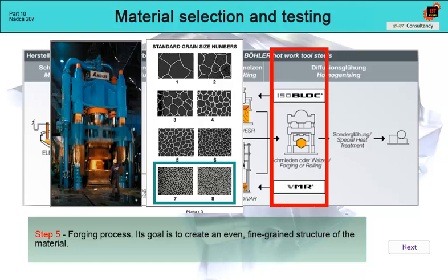Failure to comply with the grain size when receiving the material in the tool shop is a reason to reject the material at the input and replace it with new material. All costs associated with this should be borne by the steel supplier. However, it is also necessary to realize that the grain size can change as a result of heat treatment or tool use. Therefore, this parameter must be evaluated at the input, not after the insert is damaged in the foundry